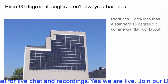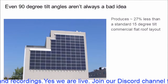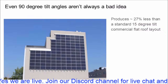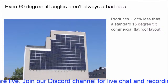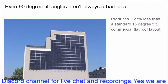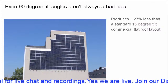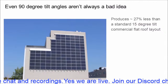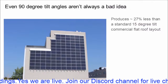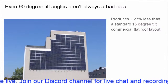You can find solar arrays bolted 90 degrees down the sides of buildings, such as in New York City, where electricity is expensive and rooftops are cramped, or for off-grid power in Canada to avoid snowfall. Similarly, at a shallow tilt angle, the north side of the roof isn't off limits. So while east and west facing solar arrays are perfectly fine site selection spots, and even north facing solar arrays in some circumstances are acceptable, most solar in the northern hemisphere faces south.